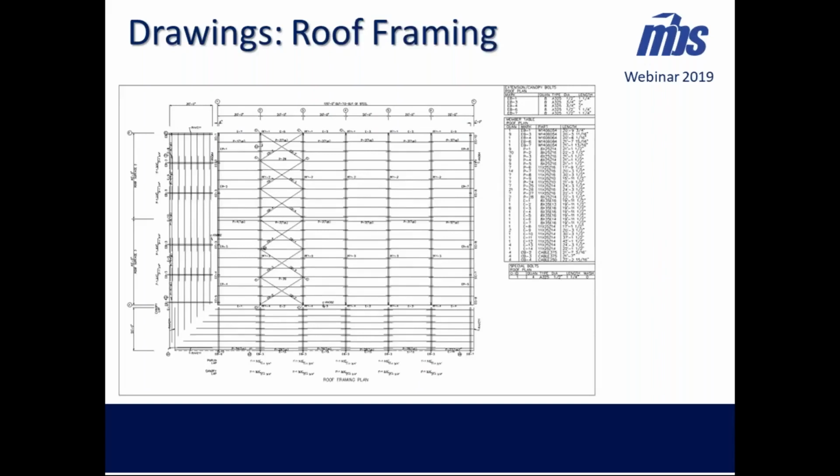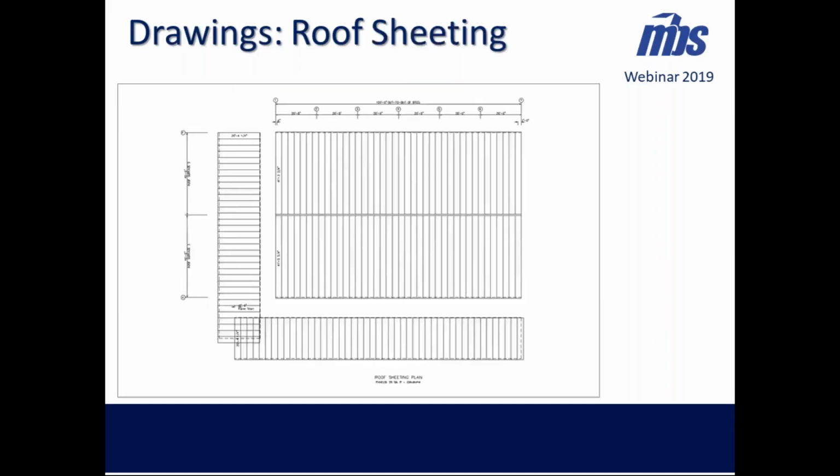We are currently on our way to doing hips, yes. We are detailing these purlins trimmed back, as you see. We have the column supports out at the ends. Here's your roof sheeting. Yes, I know we need to work on the sheeting laps. We will get those in there. But you have your sheeting for both your canopies coming out there.